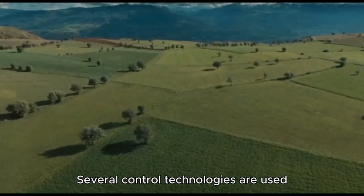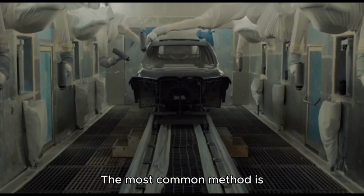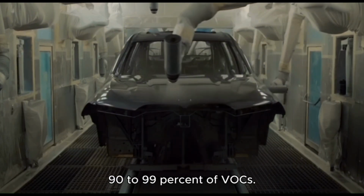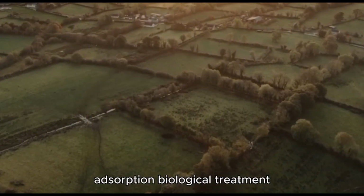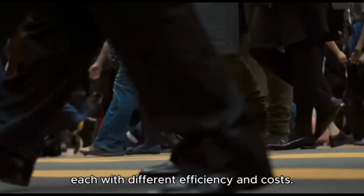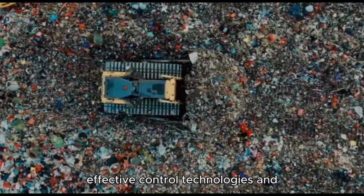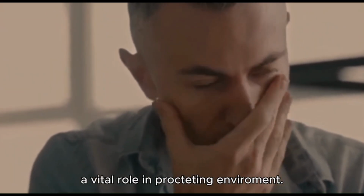Several control technologies are used to manage these emissions. The most common method is adsorption using activated carbon, followed by thermal oxidation, which can remove up to 90 to 99% of VOC. Other approaches include adsorption, biological treatment, and spray with air recirculation, each with a different efficiency and cost. While VOC emission cannot be completely eliminated, effective control technologies and sustainable practices play a vital role in protecting the environment.